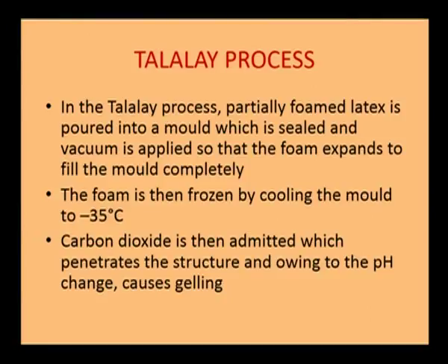The next process is the Talalay process. The Talalay process is very similar to the Dunlop process, but some of the steps involved in the Talalay process are extra, and with that difference it is standing first in the market. In the Talalay process, partially foamed latex is poured in a mold which is sealed and vacuum is applied so that the foam expands to fill the mold completely.